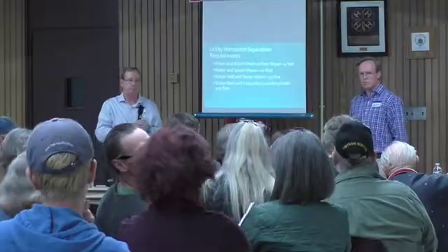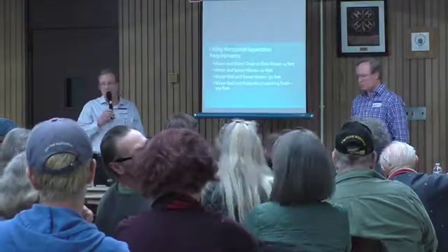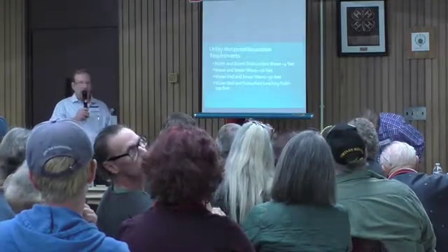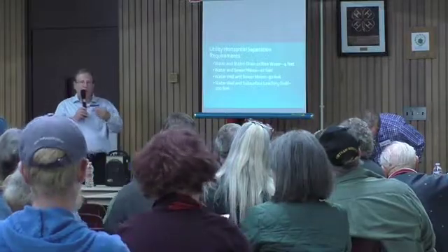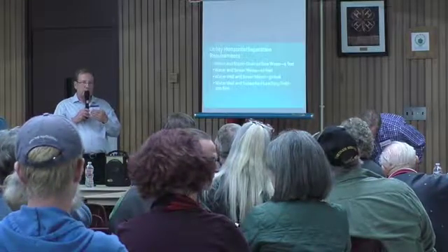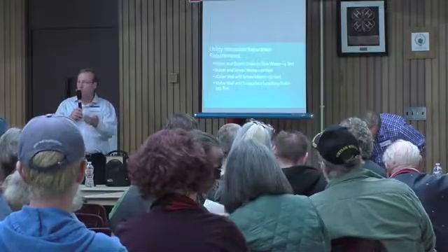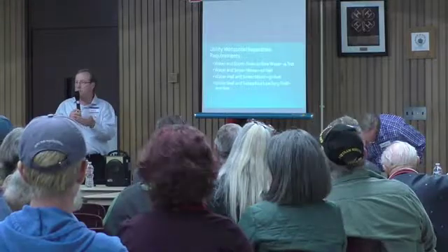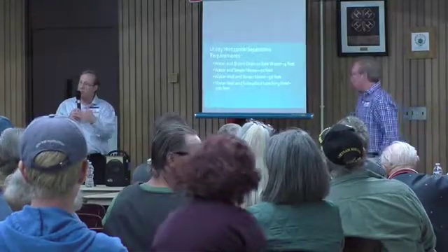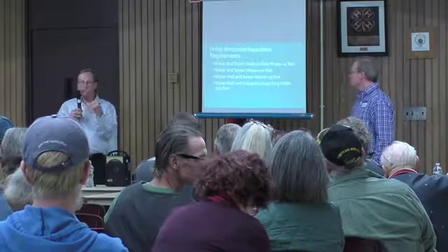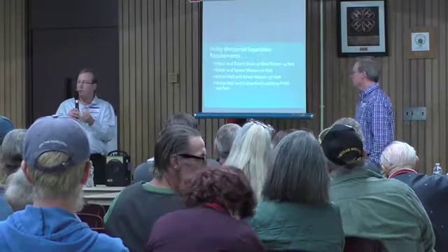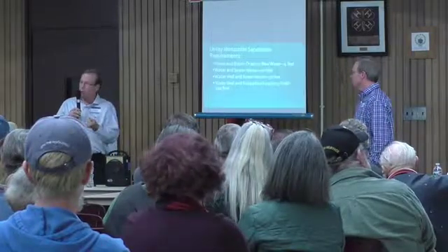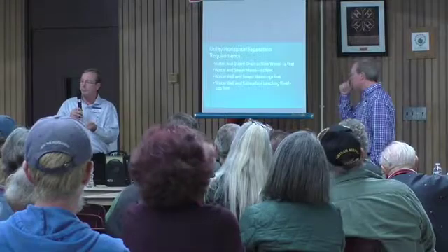Can you speak to what happens when the power goes out? The water keeps running, nothing happens. The only thing that happens is that in the area of town where power was serving the wells, they wouldn't operate. However, under most circumstances, a number of the well sites and treatment facilities would be equipped either with standby generators or at the very minimum with facilities to accept portable generators that could be brought in.